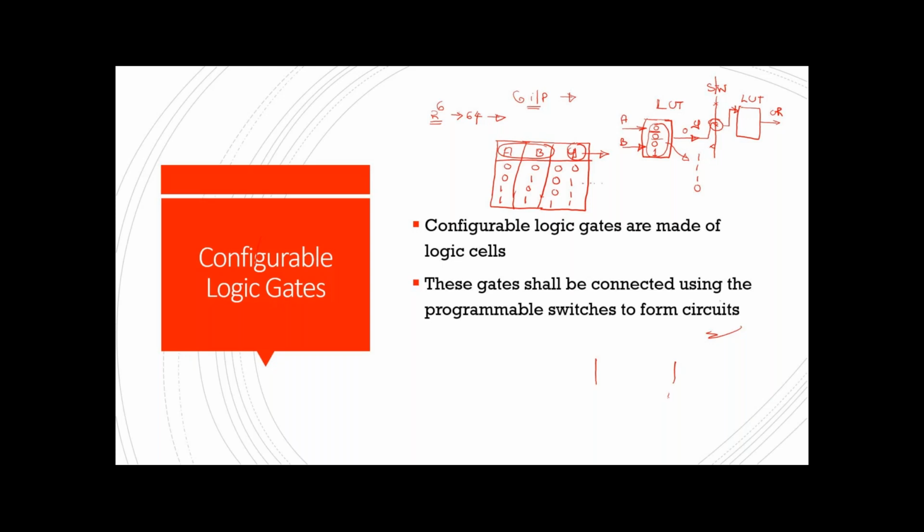When we say ASIC based designs like Snapdragon and all, those will be produced in millions of ICs, right? Not in hundreds of ICs. Once they deploy that Snapdragon, it's millions. But for a base station based application, it's unnecessary effort actually. The amount you pay to the verification engineers and physical design engineers will be huge. If I consider that cost, it's negligible when I deploy it on the FPGA.